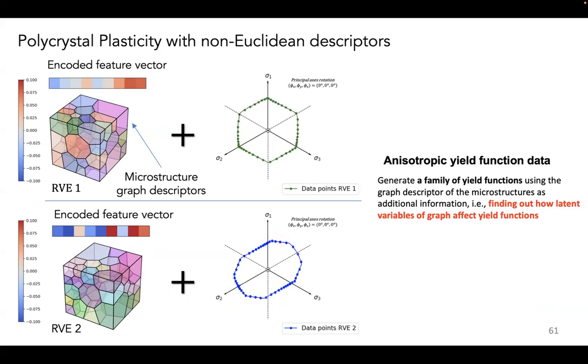That would be different than the parameterization strategy where I'm just trying to change each increment. I don't have a right answer for that, but I would still recommend that if you deal with polycrystal, you use the pi-plane, for a very simple reason: you can see the symmetry a little bit easier. And when you rotate the principal axis of the polycrystal and run a new simulation, you can see it evolve. So that can give you some intuition of what is going on.